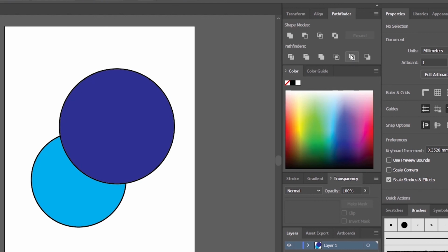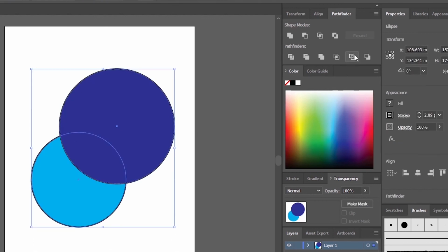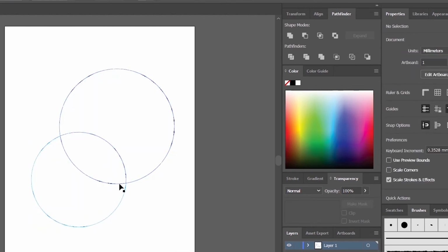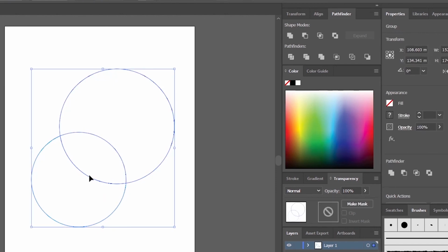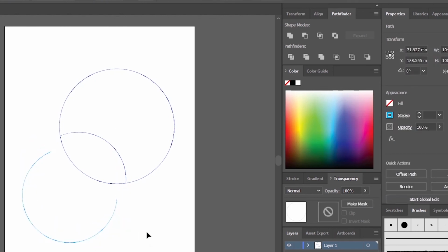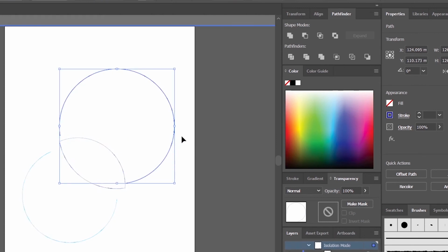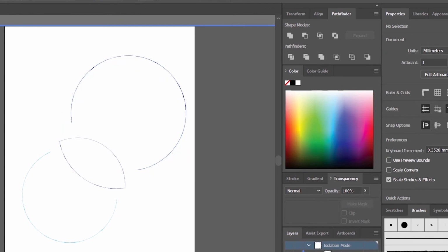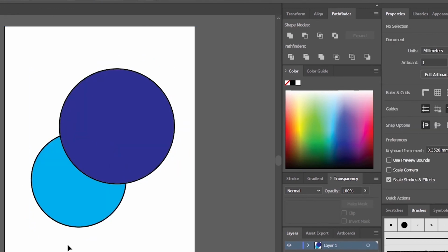The next will be the outline tool. Once we click the outline tool, all the lines on the shape will remain, but the inner colored part will be removed. So once you click it, you can see there's only the path left here. So we ungroup. You will find that all the paths can be removed and separated here. Alright, undo.